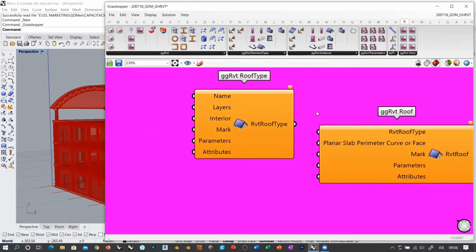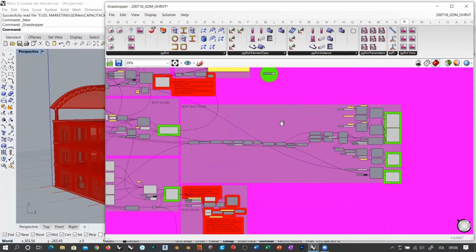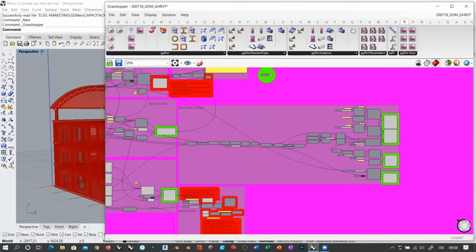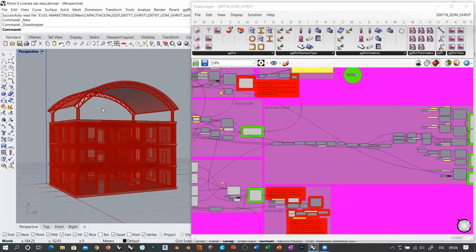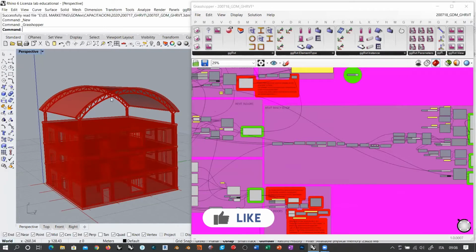And actually, in Revit architecture, roofs are more or less floors. So basically, I prefer to create a different roof, something like a vault here, which is held by two truss beams, two huge truss beams, with an arc shape.